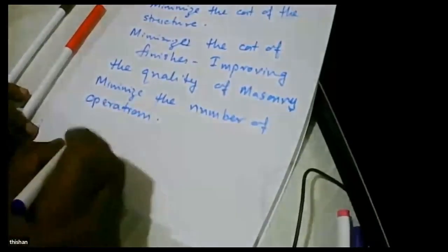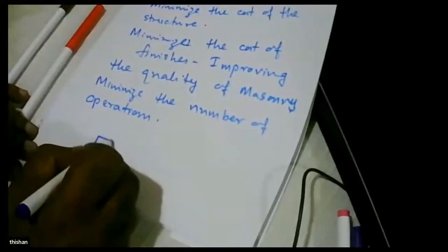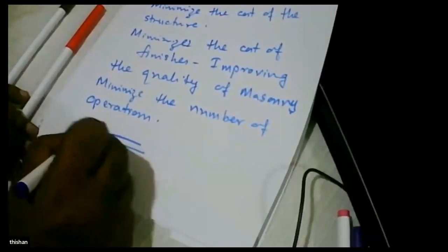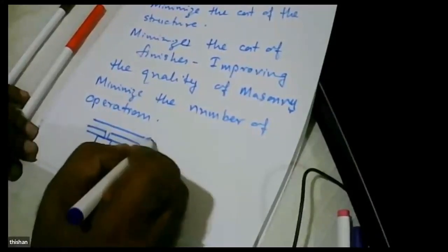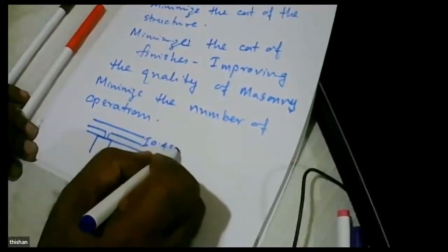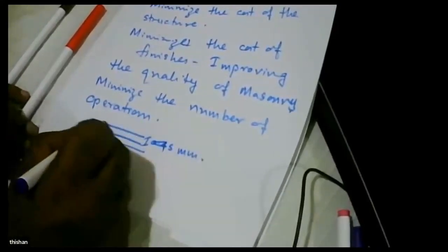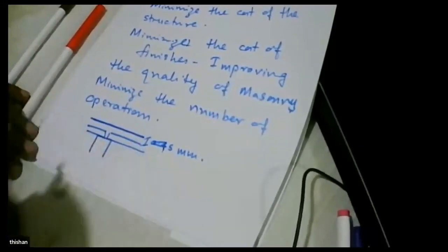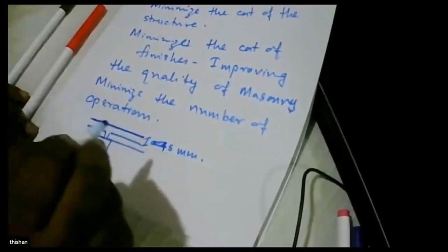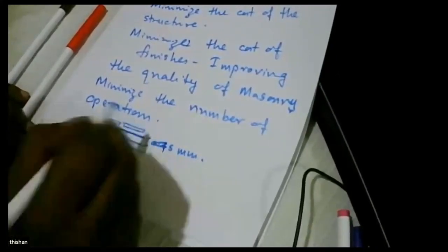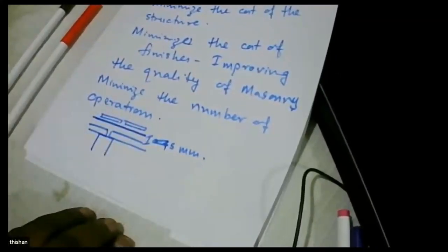So that's where I told you that when we are laying this, because we are doing only a thin concrete, 45 millimeters, we can do it slowly and make it a good finish, so that the tiles can be laid directly on this. So those are all different possibilities of this method.